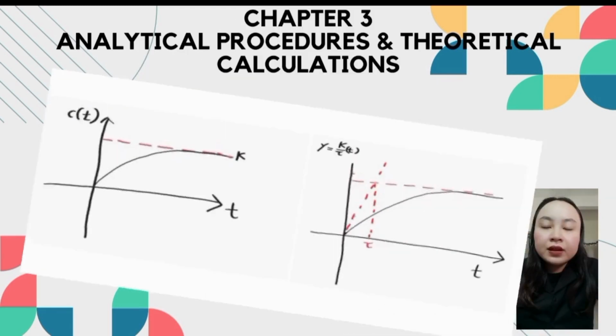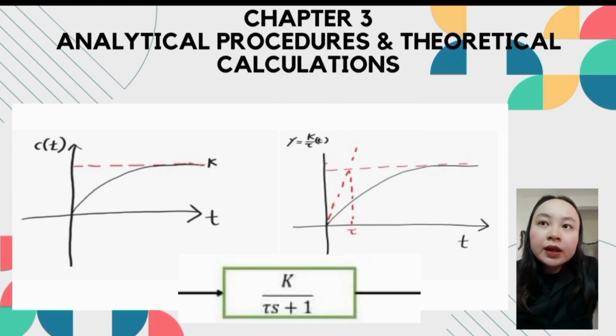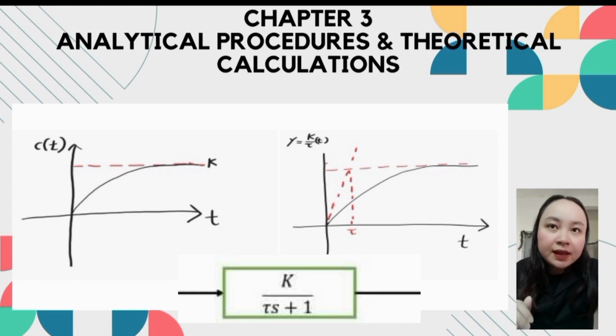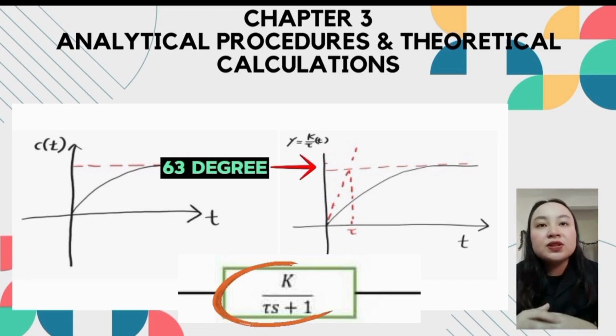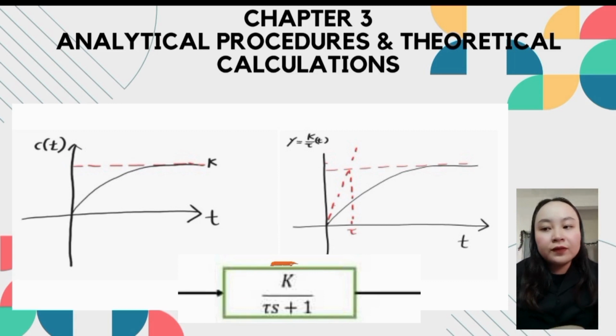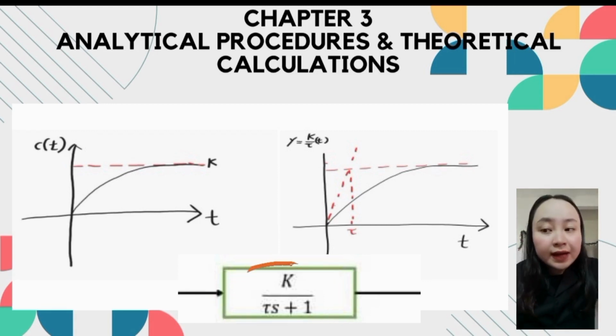For the next picture, we got the graph diagram. The transfer function is given by referring to the graph, where Q is proportional to the time, and tau is the time going up to reach 63 percent. So the transfer function of the thermostat valve is K over tau S plus 1. From the graph, we got that transfer function.